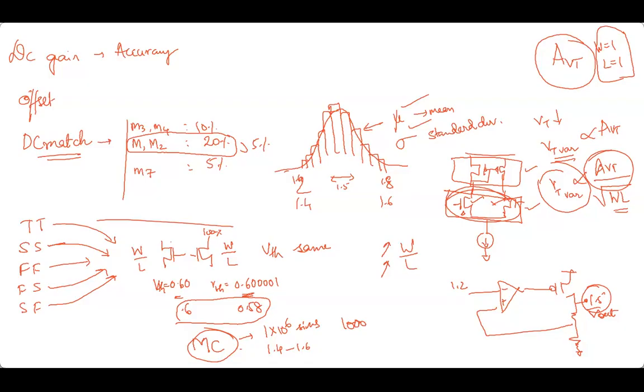Let's say earlier the size was 1 by 1. Just giving an example, you can typically increase it to 10 by 10. Even that's very much allowed. And usually you may not see a lot of negative effect on your circuit. It will still work fine. With that, you will be able to reduce the VT variation by, let's say, 10 times, which is a very significant number.